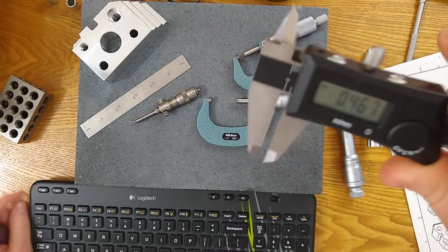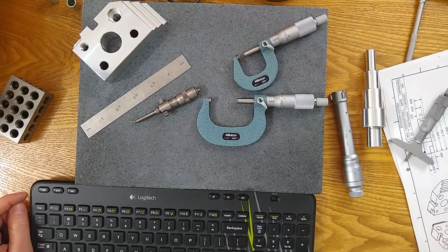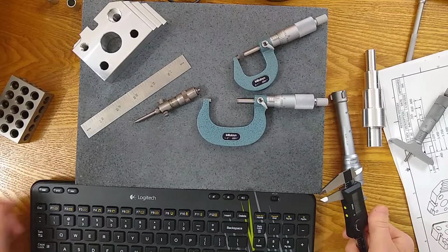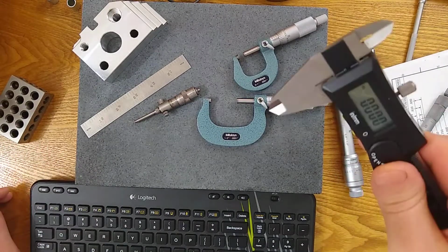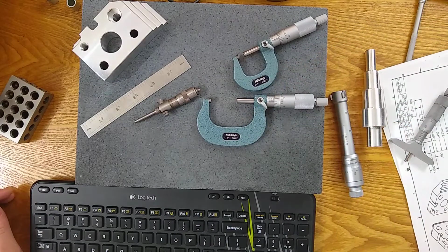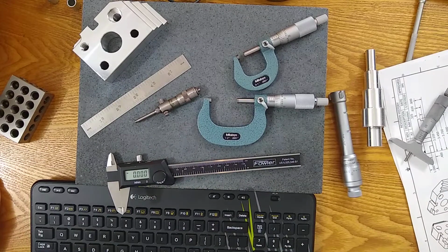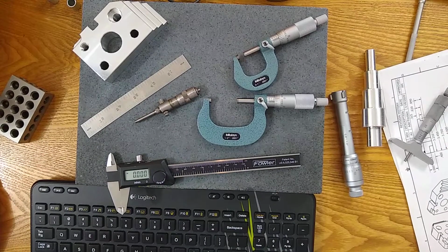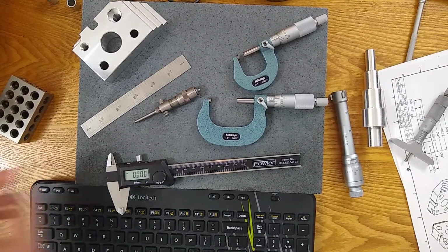And we know every caliper measurement we take is plus or minus 2 because of the accuracy of the caliper. So we could be out of tolerance by 1,000th, right? If you're at the extreme plus on your caliper, which could happen, calipers are not the most accurate gauge. So what do we do in this situation? We're going to re-verify with a micrometer.